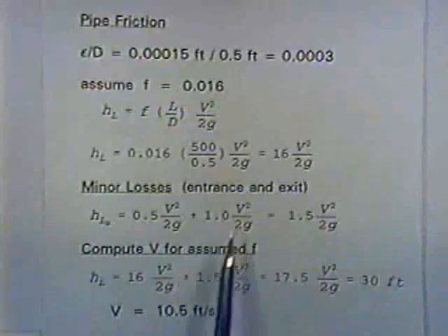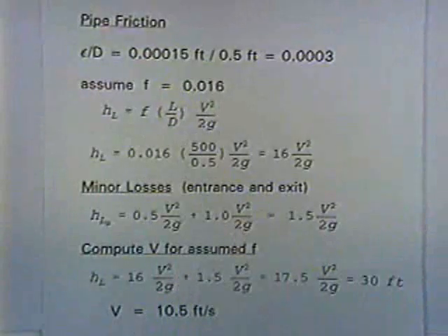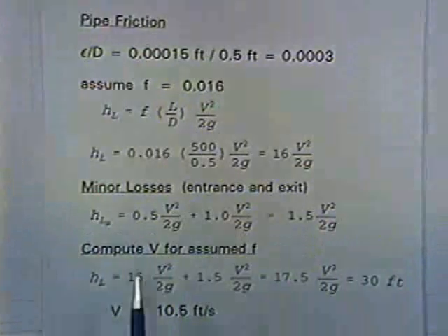You're going from some significant velocity in the pipe to essentially zero, or still tranquil water in the reservoir, so you're losing all of the velocity head. And so the coefficient's 1. We're just losing the velocity head as we exit into the downstream reservoir.